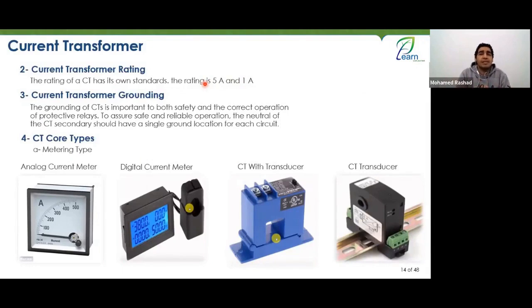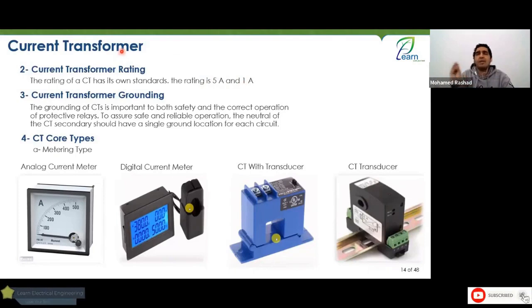It's always the CT ratio that is 1,000 to 1 or 1,000 to 5, 500 to 1 or 500 to 5, 3,000 to 1 or 3,000 to what? Or 3,000 to 5. Great, so what does this mean? The secondary or the transformation ratio is always such that the secondary current is either 1 ampere or 5 amperes. Nice, good. So what did I just talk about? A small part of the transformation ratio, and I haven't talked yet about the other parts, right?